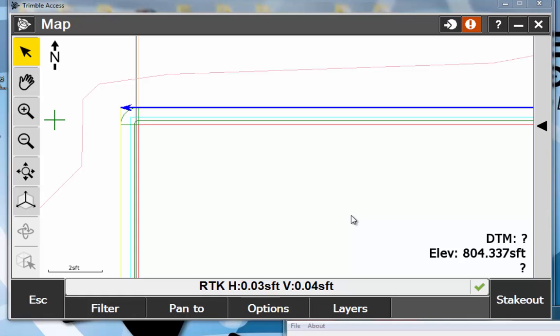I don't have to stake it. I don't have to open roads. I can do it in general survey. But the disadvantage we get with DXF files is that I'm not getting a continuous alignment profile, right? I'm basically just getting a line segment, a curve segment, a line segment, a curve segment. That may or may not be bad depending on what you're trying to do, but the more I worked with Brian through some of the staking stuff, the more I'm a believer in using the alignment method, where maybe the DXF is just more your reference.